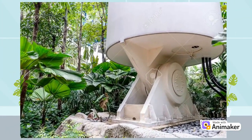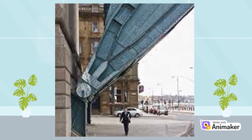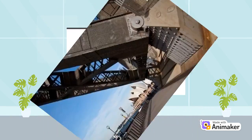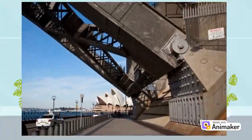movement. The rotation of pinned support or hinged support is allowed in only one direction and is resisted in the other direction. Hinged supports are also used in three hinged arched bridges with two supports at the ends, and a third hinge is provided at the center of the arch, which is called an internal hinge. The figure below shows the hinged support of Sydney Harbour Bridge.